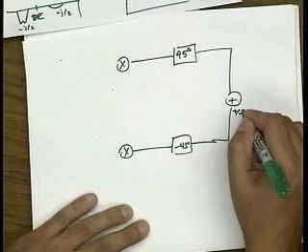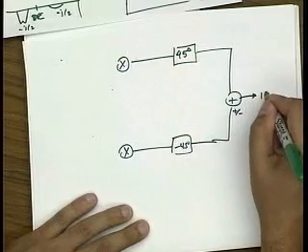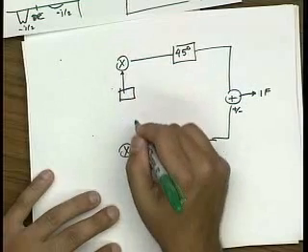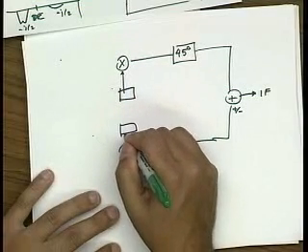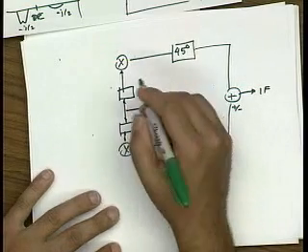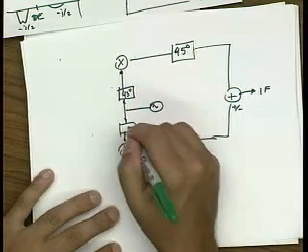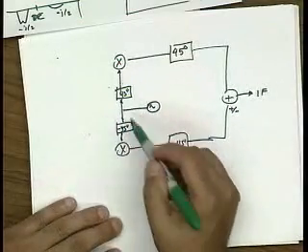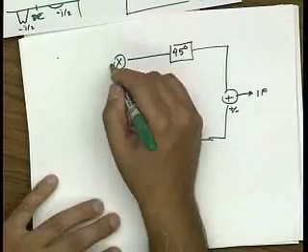So this could be plus or minus depending on if it's upper side injection or lower side injection. And in fact, even for the LO itself, I can start out from a single LO, phase shift it by 45 degrees and minus 45 degrees. So this produces in phase and quadrature phase, I and Q.